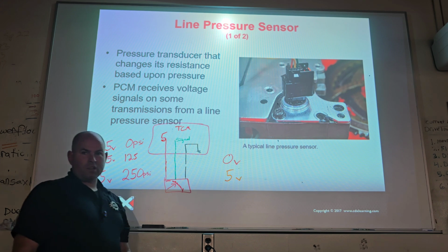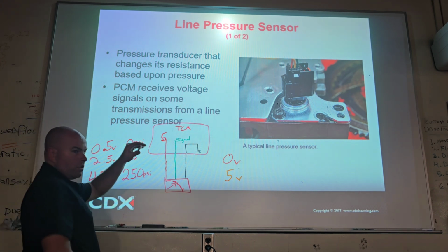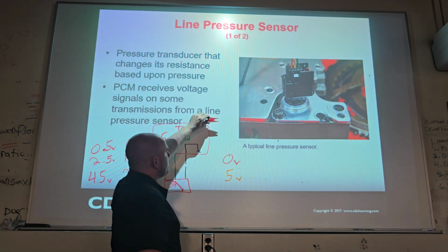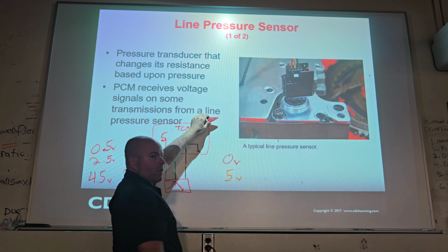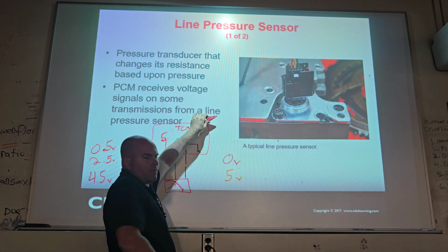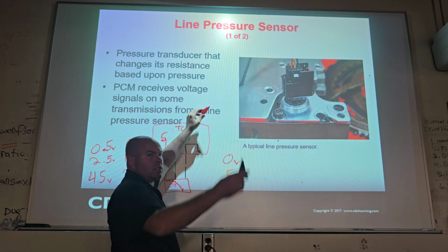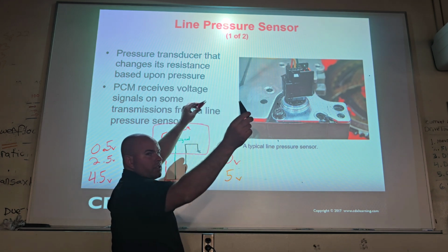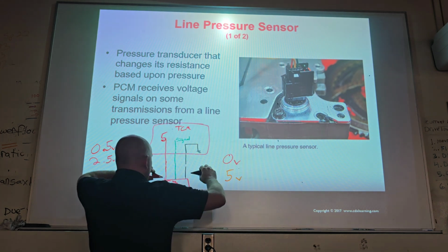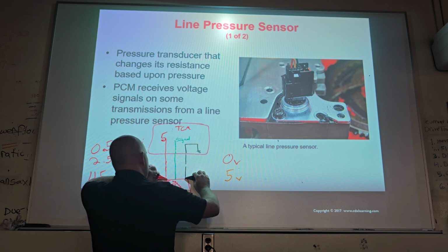That would also read 0. You believe me? Try it sometime. Hang this on your red battery terminal and hang this one in thin air. Firmly planted in thin air. It'll read 0 volts. It doesn't mean that the positive doesn't have voltage. This measures voltage difference, right? This is voltage differential. So if it's reading 0 volts, then you'd be like, okay, hold up.